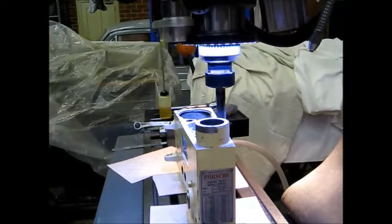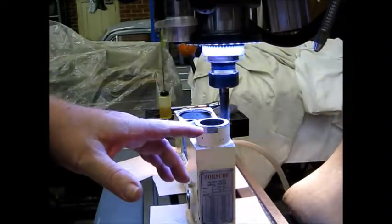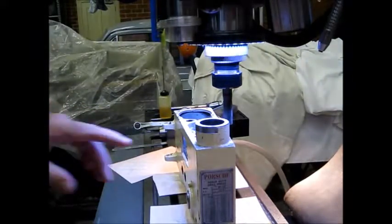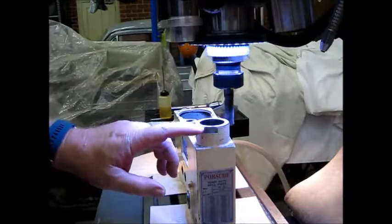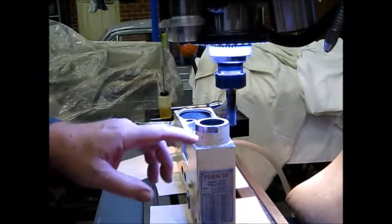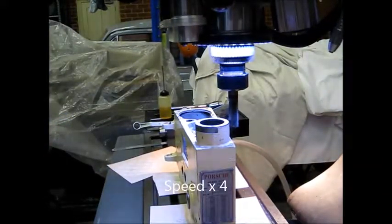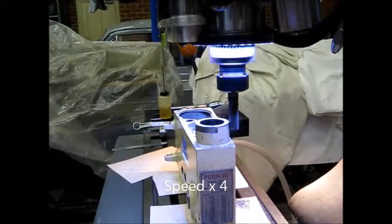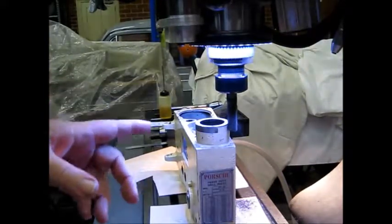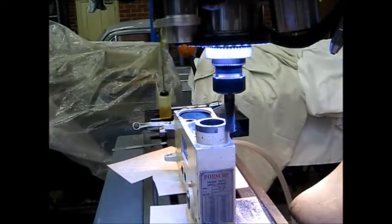I'll probably speed this part of the video up. Here it's starting to cut, so I'm pleased I didn't change it. I think there's some draft on here from the casting, so I suspect we will pick up more and more material as we bring the end mill down. I can ready the next instruction on the MDI that it'll follow on as soon as we get here, so I'll drop it down another 10 millimeters.